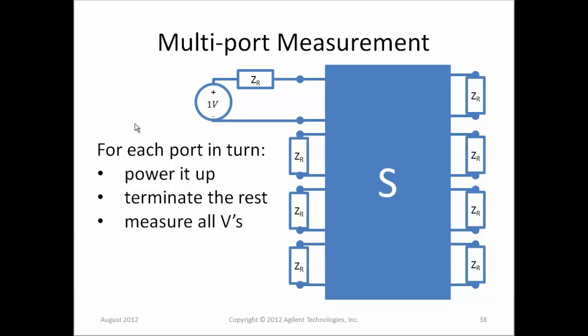And this sort of thing is very useful in high-speed digital, where you have maybe a victim channel going from ports 1 to 2, and 3 aggressor channels going from ports 3 and 4, 5 and 6, 7 and 8. So this is very typical. This particular one is single-ended. If it were differential, then 1 to 2 and 3 to 4 would be your differential victim channel, and 5, 6, 7, 8 would be the differential aggressor channel.